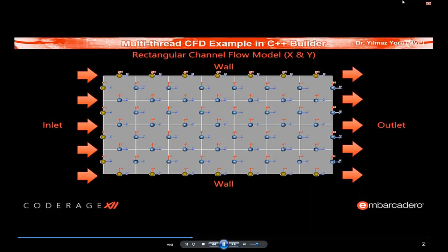And at the wall, those yellow nodes are zero, because at the wall there is no velocity. That means both U and V are zero there. At the front, there are initial velocities, so U is zero in all front velocities, and V has a value. We used a uniform flow section. As a result, with the hidden velocity nodes, you can use this node design model to calculate velocities and pressure in the fluids.